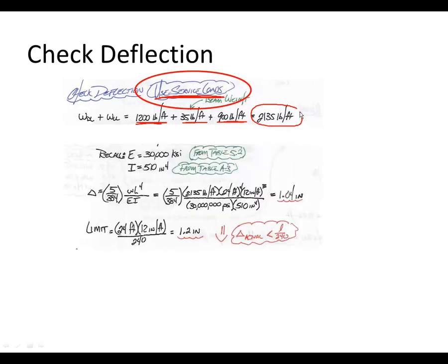In our deflection equation, we are going to use a distributed line load, which is usually what we're going to use with beam design. If you had a concentrated load, you might have to split this into two pieces as we did with timber design. But because we simply have a distributed load, we can get away with just the one equation here. And recall that for a distributed load, you can find these on the common load solutions.